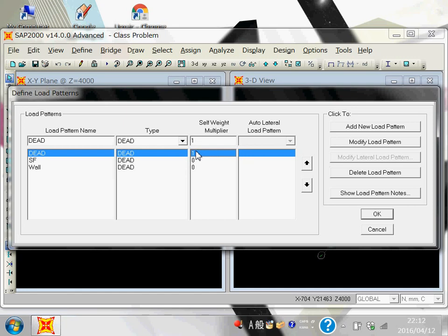For example, if you want that, no, I will not give the thickness of wall, I will directly apply the wall load, like 13 kilonewton per meter. Yes. You say I will apply the wall load 13 or 16 kilonewton per meter. So in that case, you will just give the value. Don't worry. I will show you how to check it.